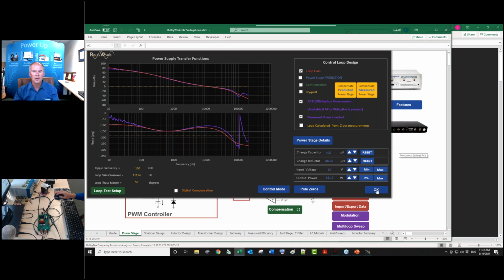Okay. What do we use for the loop gain prediction? Well, we use what everybody should be using, which is Vorperian's PWM switch model. You crank the equations, and there's that prediction. So we do not use state space averaging. I haven't used that since 1986, and life has been okay without it.